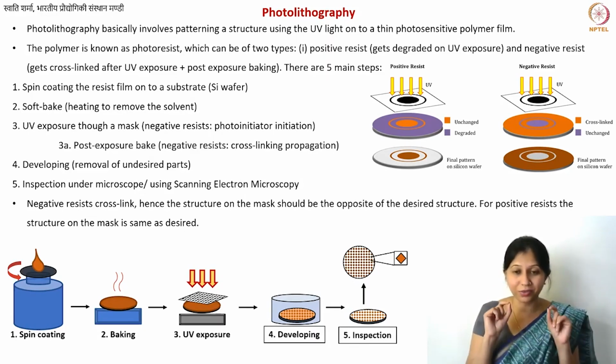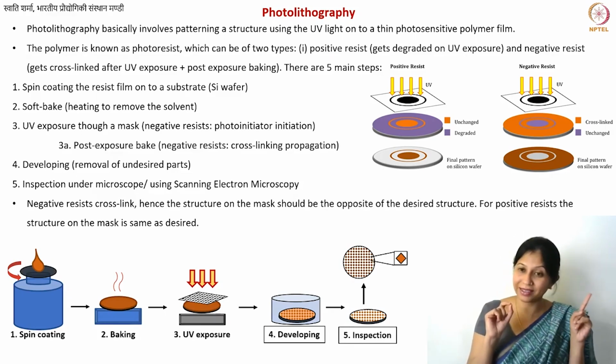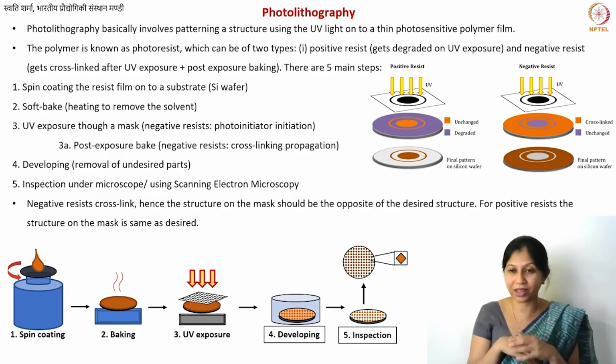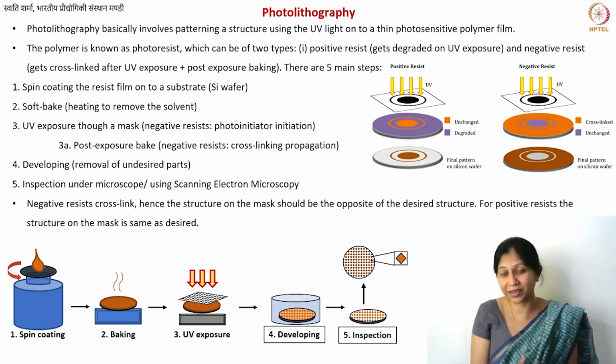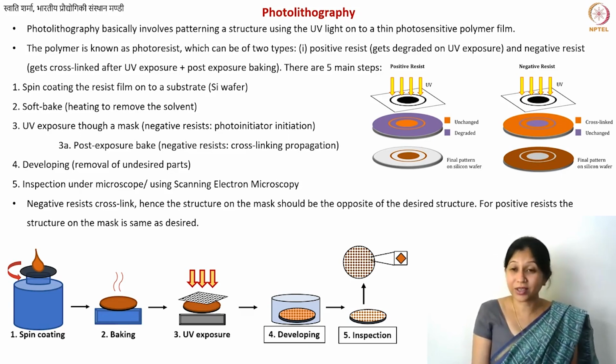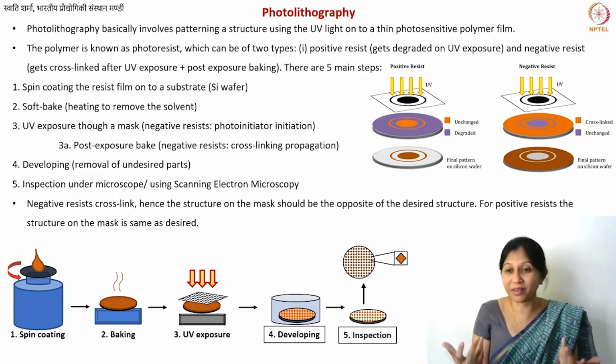Remember that these structures will be dimensionally smaller. They will be shrunk. That is the same problem we also have in large scale manufacturing. You end up losing some material because it becomes smaller. But here you can even utilize that fact, because smaller structures will have a higher surface area. So smaller the better in the case of micro nano fabrication, right?